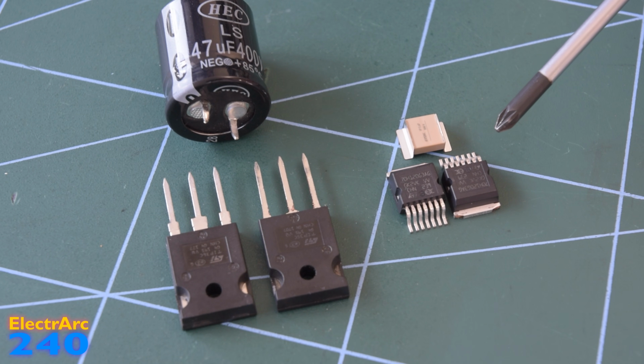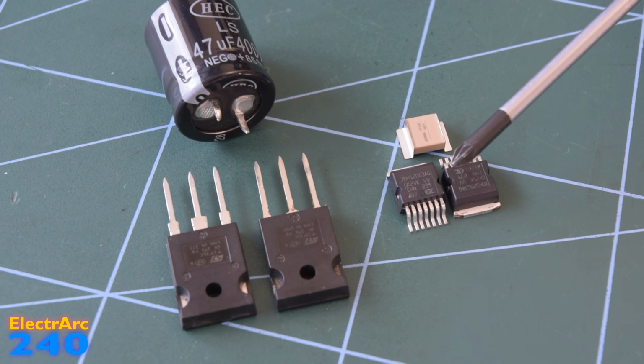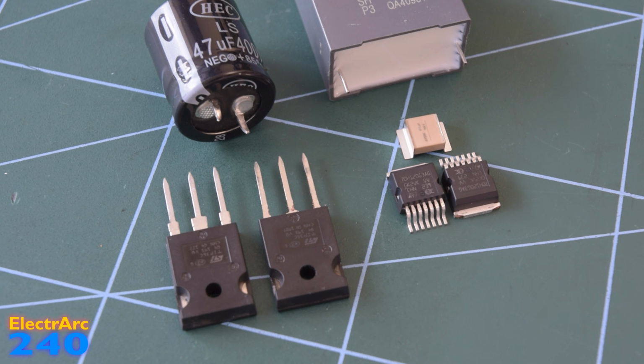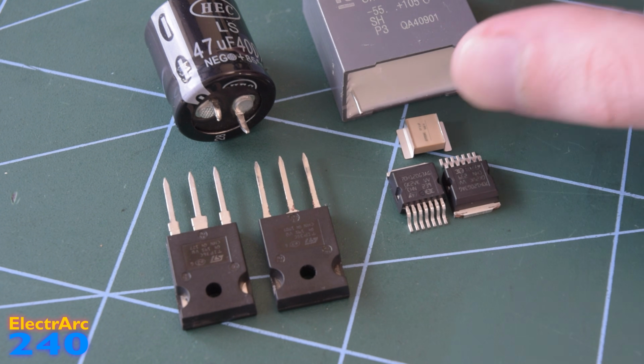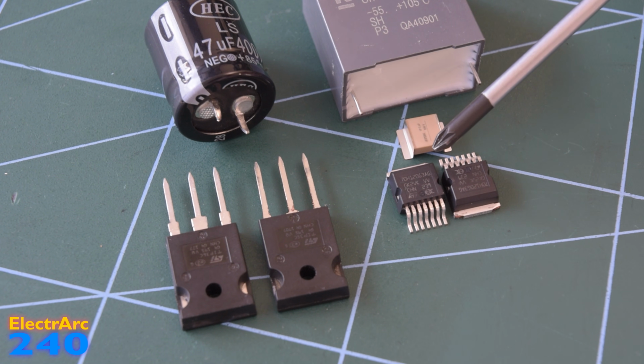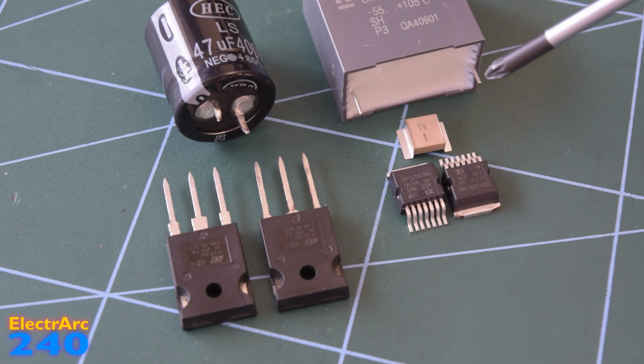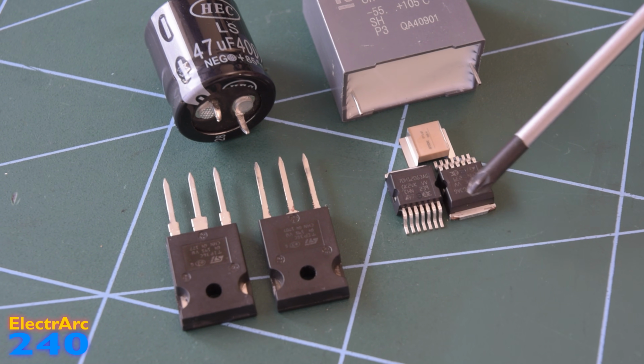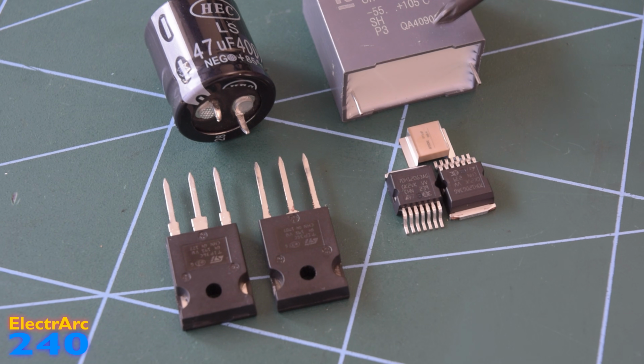If you're making something like a half bridge and you need a big capacitance, let's say you're using these surface mount devices but you have to have as much capacitance as this film capacitor contains, then what you should do is add local decoupling, so that's a smaller capacitor like this Ceralink, as close to the MOSFETs or half bridge as possible. Then this capacitance will deal with the highest frequency current, and the bigger capacitance that you can't put as close will deal with the lower frequency components.